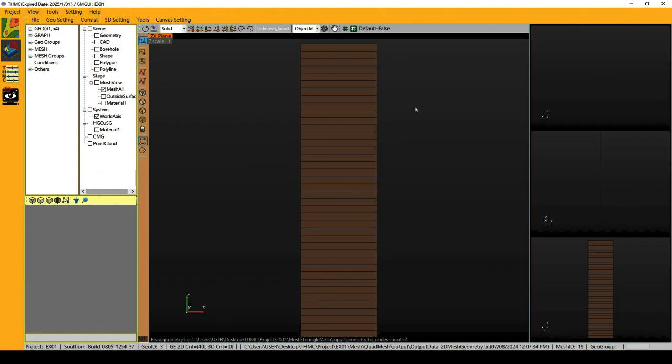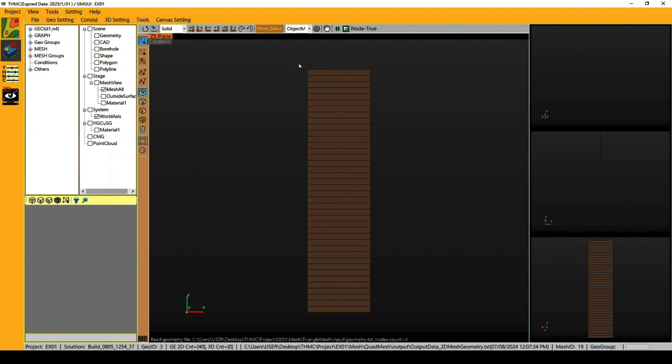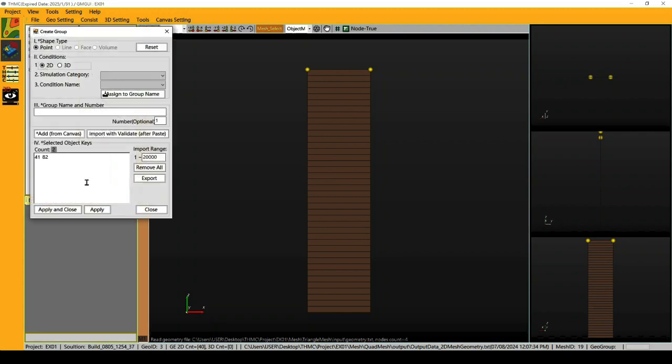If the mesh has been created, one would want to set initial and boundary conditions for the area of interest. In Benchmark Problem 1 for the initial condition, since different values were input for the top, bottom, and the rest of the area of interest, we will specify initial conditions for each of these 3 parts separately. First, with Add Selection selected on the left side of the window, choose Select Nodes. Select the nodes located at the top of the area of interest, and drag to select the 2 top nodes. The window screen appears. In the panel, select Create Group, then the Create Group window appears.